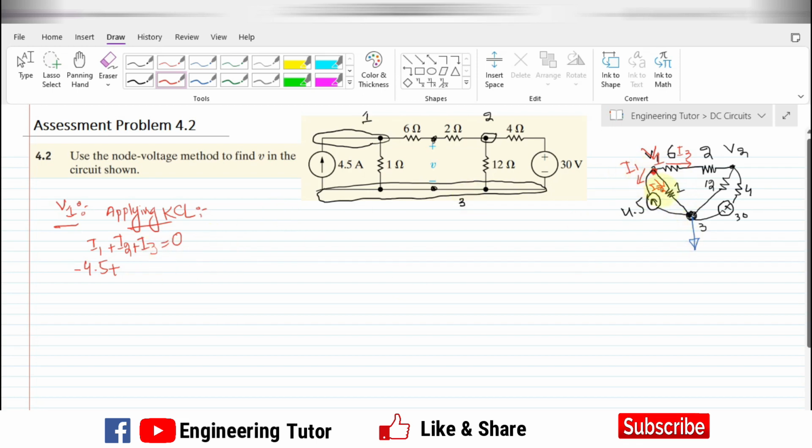Applying KVL at this branch, we get V1 minus 0 divided by 1. Similarly, the current I3 is again the potential difference divided by the resistance. These two resistors are connected in series, so adding them together we get 8. So V1 minus V2 divided by 8, this is equal to 0.